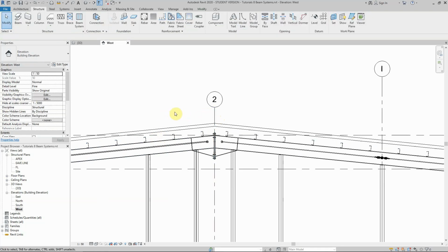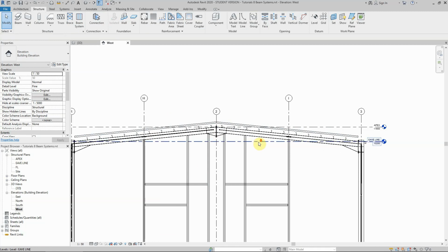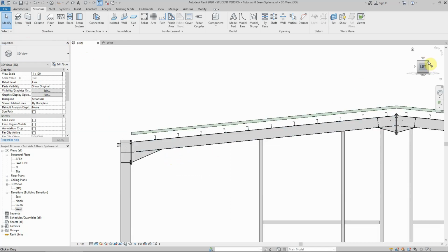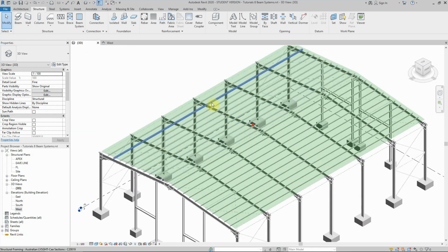Okay, we agreed during the class that the maximum length of these purlins would be about 19 meters based on different criteria that we looked into for transport, for manufacturing, for handling on site. Therefore, we agreed that we are going to break our purlins somewhere here in the middle.